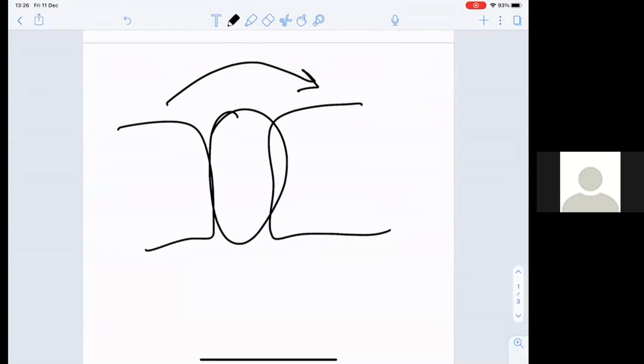And that's the same as capacitive. So that is capacitive coupling. That's how you can end up with an alternating current in the wire and a person having a capacitive current induced in them by that wire. It's also how floating transformers work and how there's a risk of electric shock to patients if they're connected to earth, even if they're not directly connected to the line or wire.